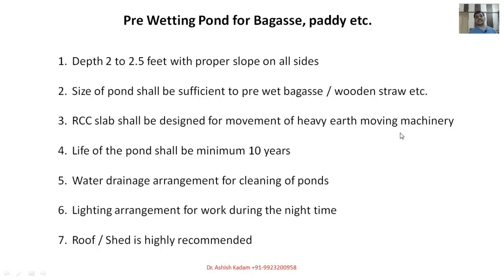And once you start getting cracks, there is a possibility of earth material like dirt, maybe sand, from the foundation mixing into your compost and degrading its quality. So we have to take the right care when designing and constructing the RCC slab. In video number 2 we have seen what the quality of the RCC slab should be. We have seen the photos of that.